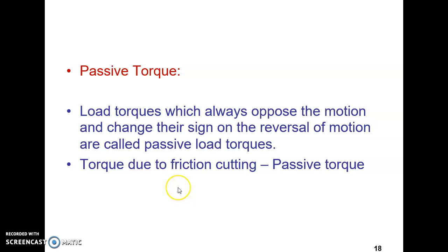Next we will see the passive load torque. Load torques which always oppose the motion and change their sign on the reversal of motion are called passive load torques. The torques due to friction, cutting, etc. are passive load torques.